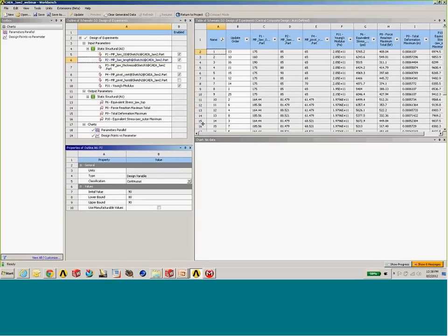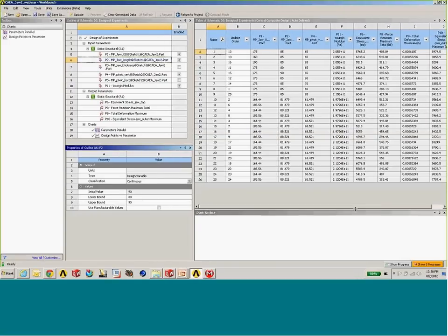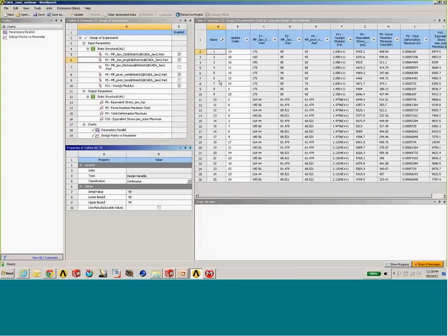If we're using the Remote Solve Manager, we kick off all these design points. Now, the reason we're doing that correlation, as I mentioned before, is that the number of design points required in a DOE is directly dependent on the number of input parameters. So you eliminate input parameters, you eliminate required design points. That correlation step becomes a nice time saver in that regard. For the parameters we're interested in, we specify their ranges and generate the design point solutions.